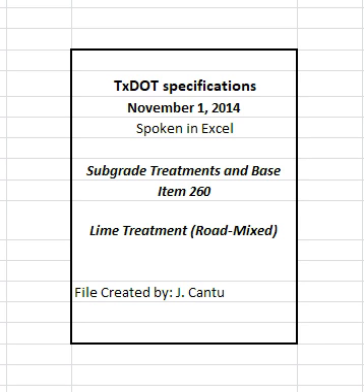Reimburse the department for subsequent mix designs or partial designs necessitated by changes in the material or requests by the contractor. Limit the amount of recycled asphalt pavement to no more than 50% of the mix unless otherwise shown on the plans or directed. 3. Equipment. Provide machinery, tools, and equipment necessary for proper execution of the work. Provide rollers in accordance with item 210, rolling. Provide proof rollers in accordance with item 216, proof rolling, when required.